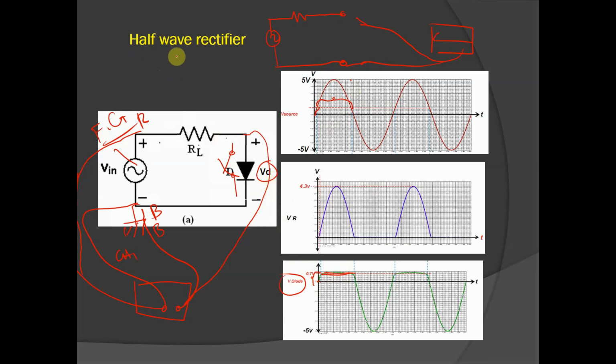It's like, let's say for example, you have a voltmeter. Okay, this is your resistor. If it is shorted here, then you measure the voltage here with the meter here. What you can measure if it is shorted is 0. That's why here it's a flat line.